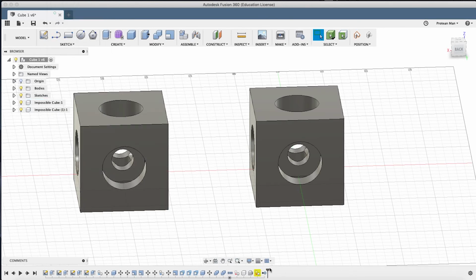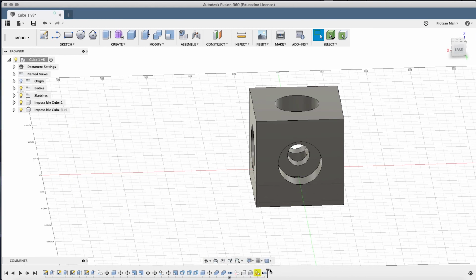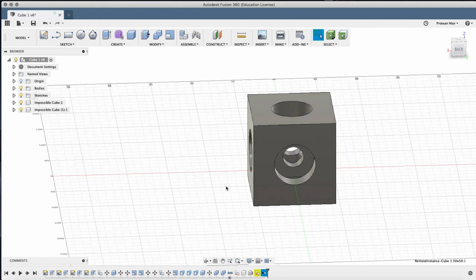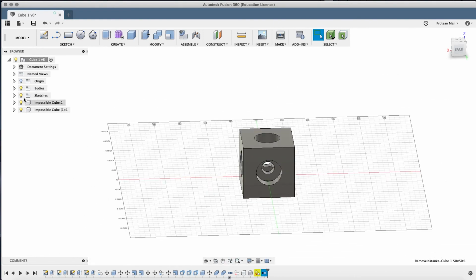So watch this. Down the menu here on the bottom, the history, it's gone right now in the menu. There's no cube one. I go back to here and it comes back. So that's a nice thing to have. You can also right click and hit delete, which deletes this actual action down at the bottom. It doesn't delete the cube one that was there. It deletes the action of removing it. So remove is a nice way to keep it in reference, but not have it disappear.